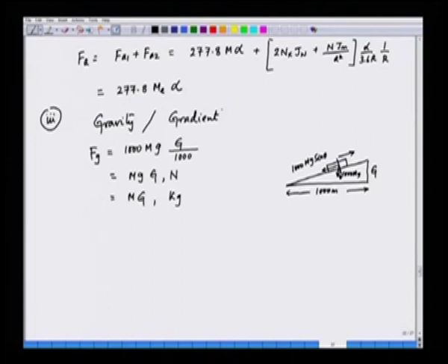So, in this lecture we have discussed the speed time curve of a locomotive. We have seen how we can calculate the overall distance travelled, and we got an expression for the distance travelled by the locomotive from one place to the other when it goes through constant torque mode, constant power, free running, coasting and braking.